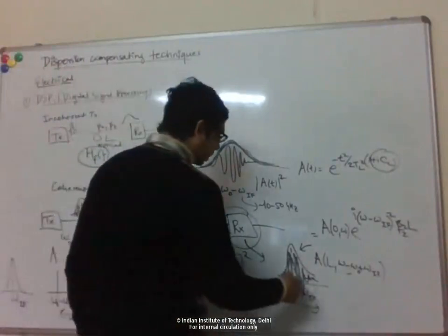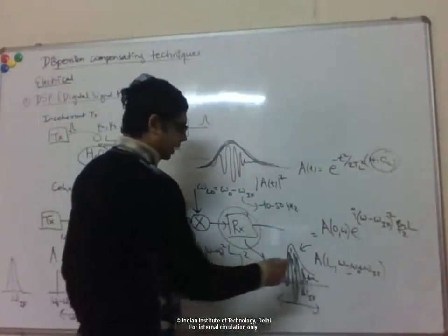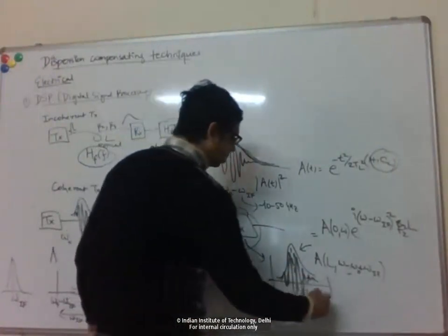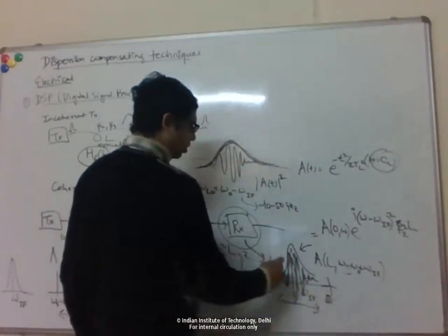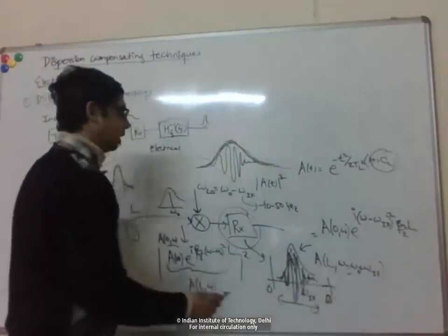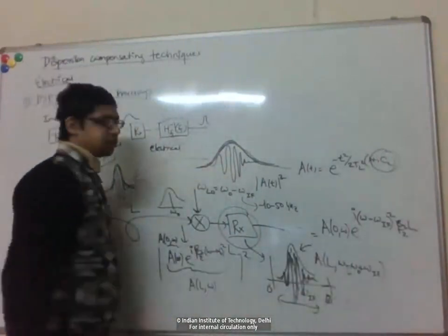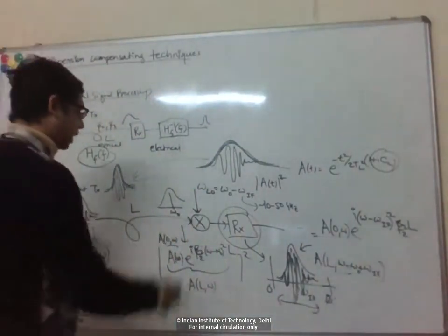Or the inverse of the pulse width. So that's again typically tens of gigabit per second, so tens of gigahertz, right? So this will roughly, let's say, go from 0 to somewhere like 50 or 100 gigahertz, right? So basically your photodetector bandwidth has to be more than that. So typically the photodetector bandwidths are in this range, let's say 50 to 100 gigahertz, which are used for high capacity systems, right?